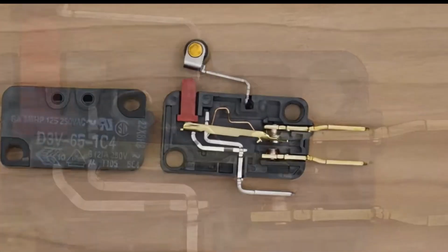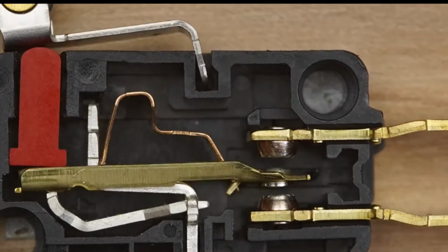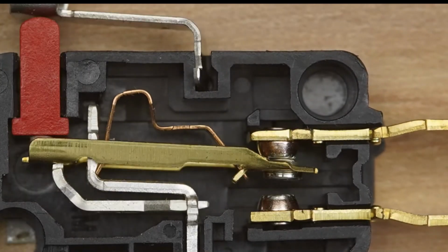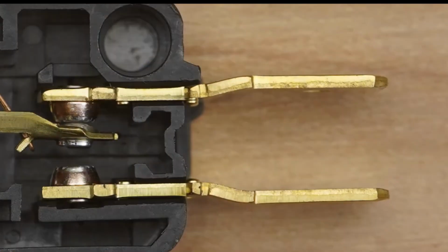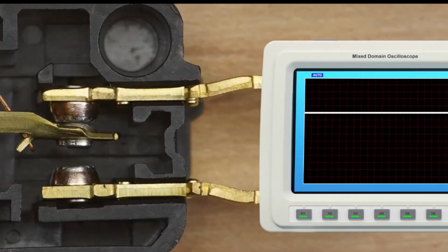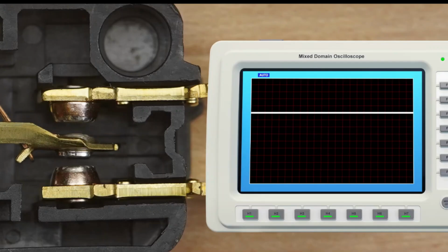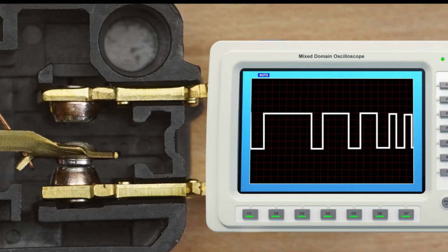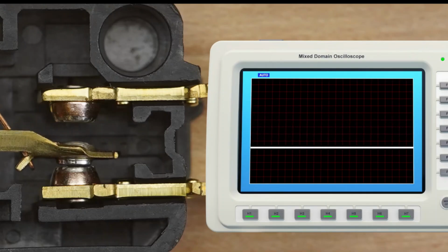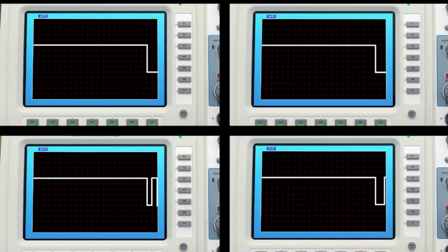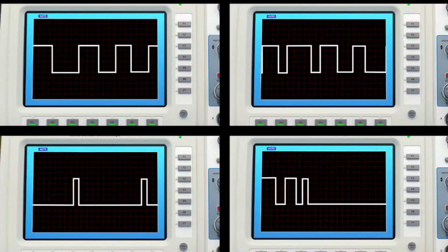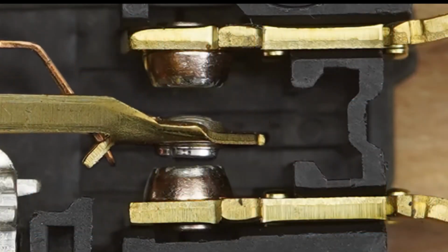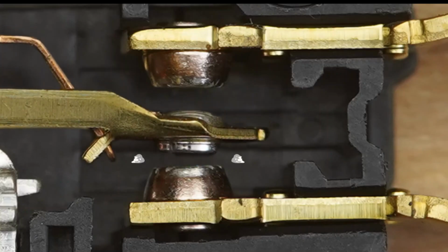So let's take a look at what's inside. We can see here, there's the switch bounce, and there's the switch bounce again. And it's simply because we have springs in there. And what will happen is that that's going to cause more than one signal being registered. We see here on a scope, but the same thing would be registered on a digital controller. And so what we're trying to do is avoid that because the spring bounce is going to be different for every different device. We can't really predict what it will be.